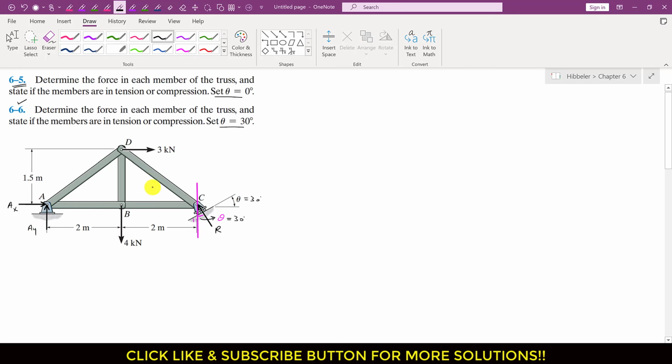Now we will start this problem by finding the reaction forces, that is AX, AY and R. We are given this 3 kN force at this joint D, but at this particular joint we have three unknown forces, that is FAD, FBD and FDC. So we cannot start the solution from this particular joint D.